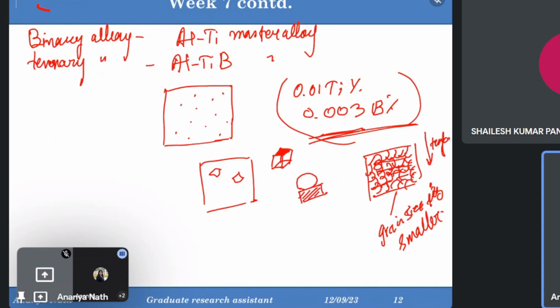So the shape, size, geometry, morphology or topology of the face is important. At the same time, how many faces there are is also important for the nucleus to nucleate. This is why there was another concept of facet. The number of facets on which aluminum can nucleate will be more for blocky type morphology.